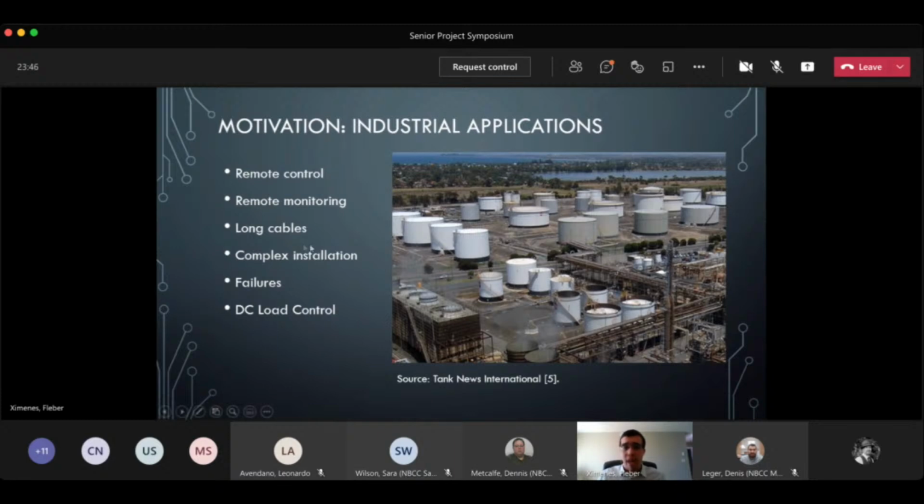And it does require long cables and complex installations because the equipment is located too far from the control center, and the cables have to run for kilometers sometimes, passing through manholes, handholds, and wiring boxes. As you can see, it's an open environment here, and animals, specifically rodents, like to make their nests inside the manholes and handholds. They like to bite and chew the cables. So in my background, we had a lot of problems dealing with faulty cable circuits.